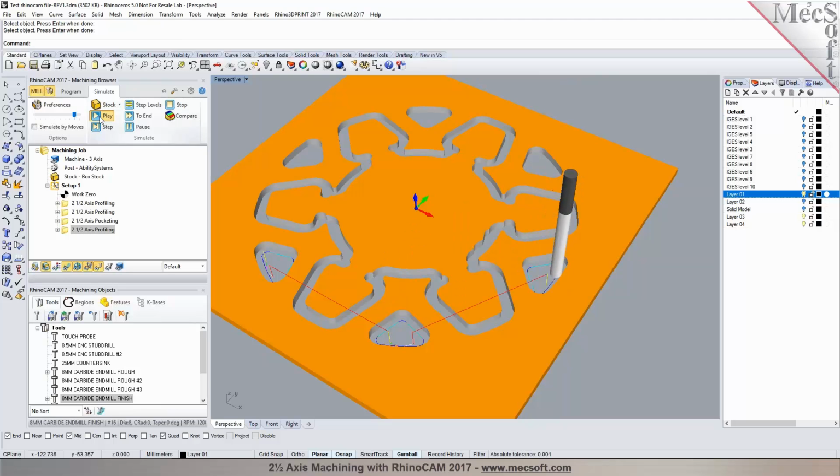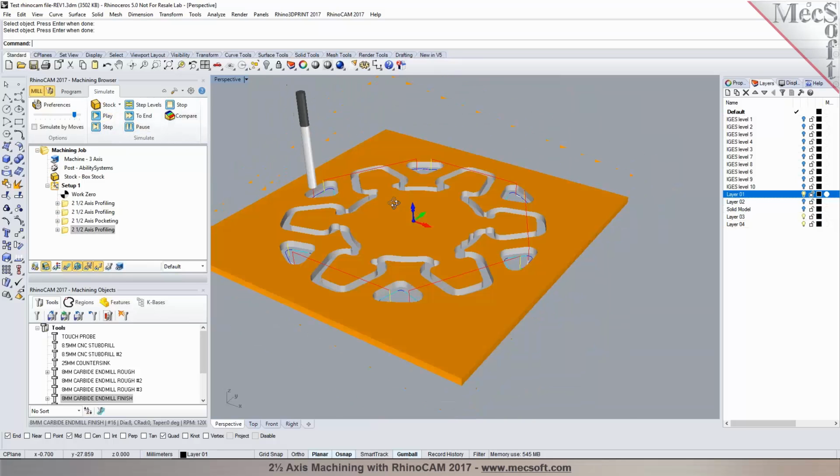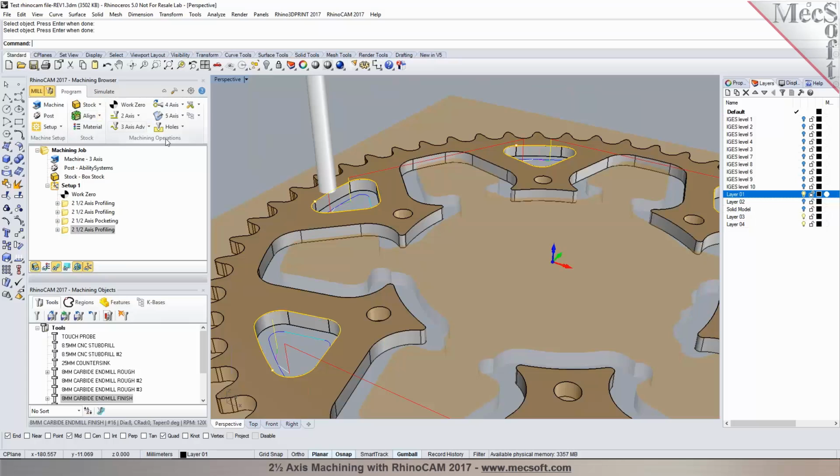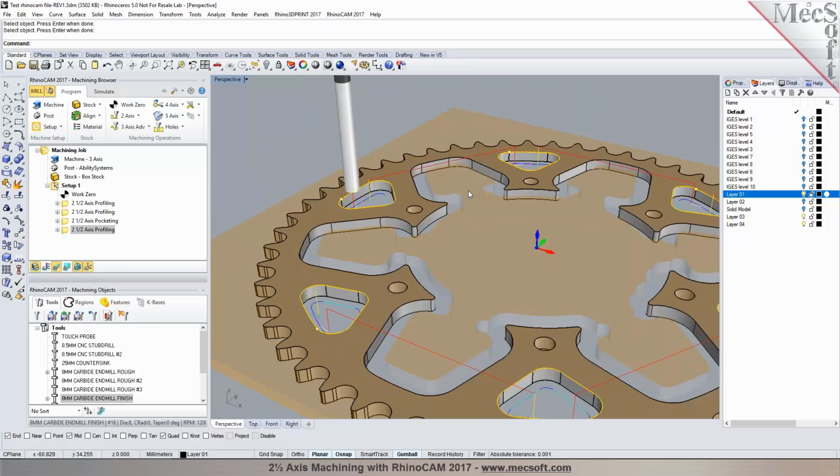And if you need to use a cutter compensation like a G41 or a G42, we could enable the cutter comp to be toggled on, and then the compensation can be done at the control. So can you actually generate the code with the cutter compensation taken into consideration?